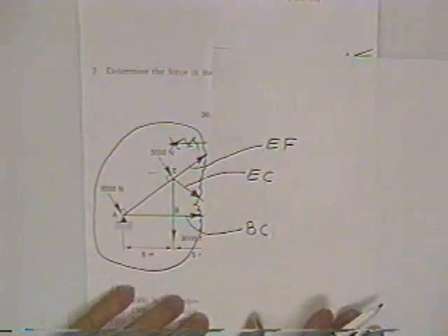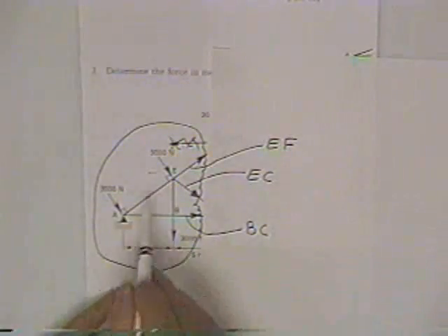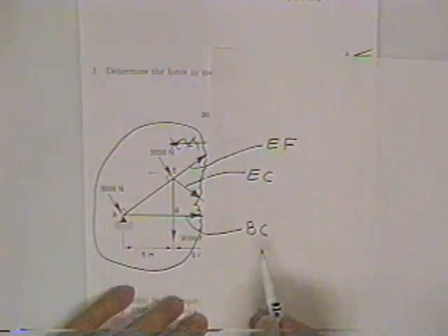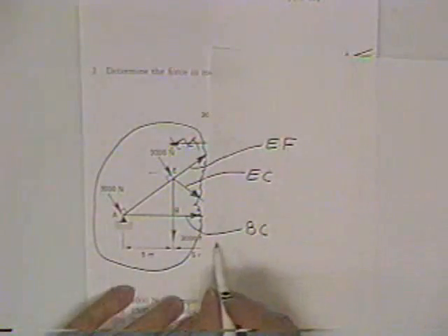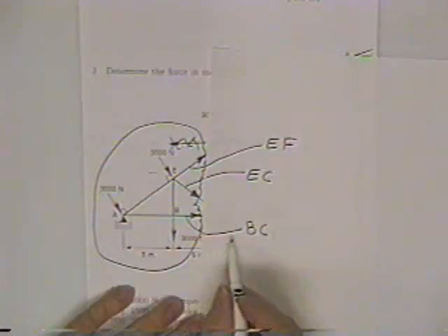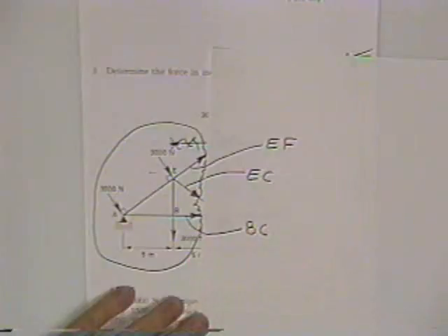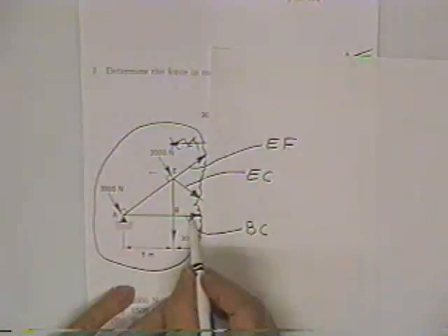Now then, it will be your job to put this little piece of steel in equilibrium by using the equations. Sum moments about any point, sum forces X, sum forces Y, all equal 0. Now here's the easy way to do that. There are 3 unknowns hanging out of that free body. It obviously is not going to just give up easy. You're going to have to do some work.